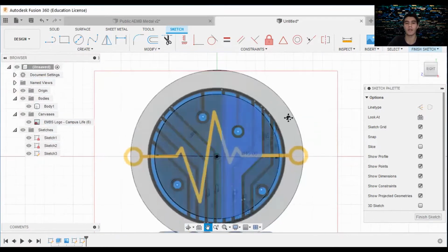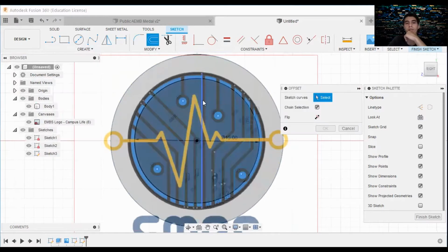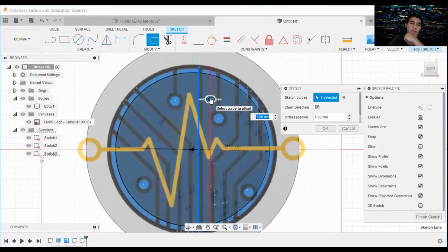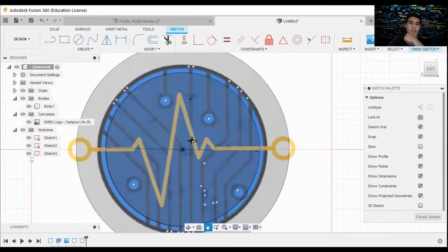And then what you do is you go here to offset, and you offset this one line across the entire canvas. And look, there you go. There's your exact line. You see it now? 2 lines, the exact same length, we just moved it across. Yeah, I see it.